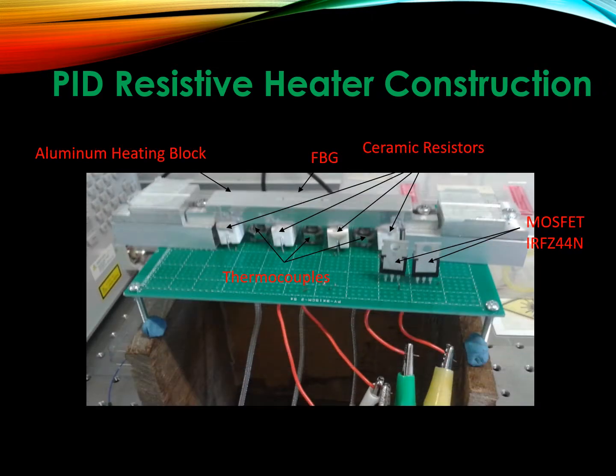The heating stage is designed to hold the FBG in position to allow heat from the ceramic resistors to be transferred to the FBG effectively and to allow the thermocouples to measure the temperature at the heating block.